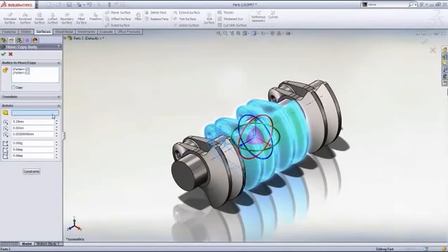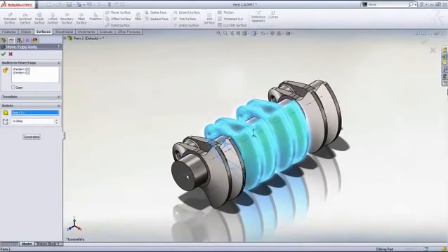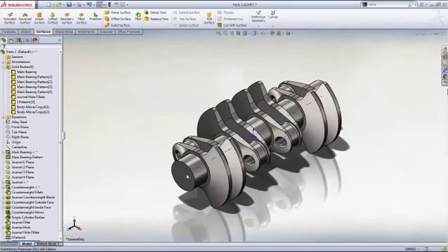To rotate about a specific axis, we're again going to utilize the temporary axes SOLIDWORKS created for us. Then we just need to specify the rotation angle, which is 180 degrees. When you're finished with the temporary axes, you can also simply toggle them back off using the same pull down. That's something I really like about them.